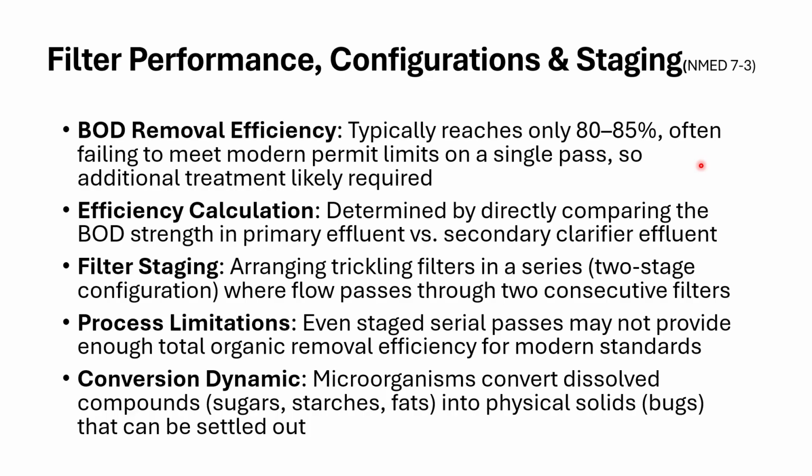If we eliminate 80 to 85% of our BOD, and we can eliminate aeration, for example, an aeration basin or an oxidation ditch, or really downsize those, that's money well spent when you think about it. By clipping off 80 to 85% of your organic load, you only have to treat the remaining 15 to 20%.